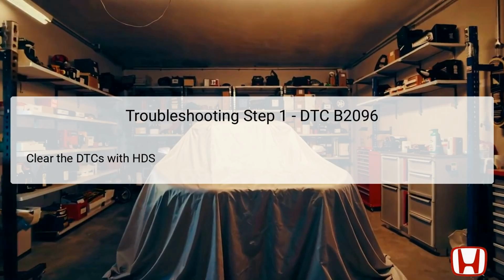The first step in troubleshooting DTC B2096 involves using the Honda Diagnostic System, HDS, to clear any stored diagnostic trouble codes. Clearing the codes allows the technician to reset the system and observe any new codes that may arise during normal operation. Using the HDS, ensure that all DTCs are cleared, which provides a clean slate for further diagnosis.